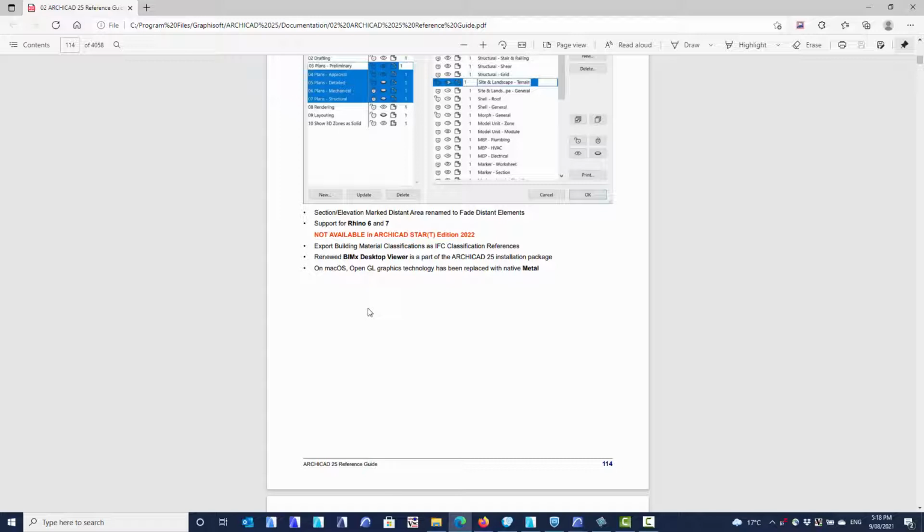So even though you're saying I've got six 3-metre beams, it specifies the length as 18 metres, because it gives a total length. In future we'll be able to manipulate that schedule and say, no, I want to show the individual beam lengths, so it will actually say you've got six 3-metre beams. It will show the lengths as 3 metres, and you've got 6 of them.